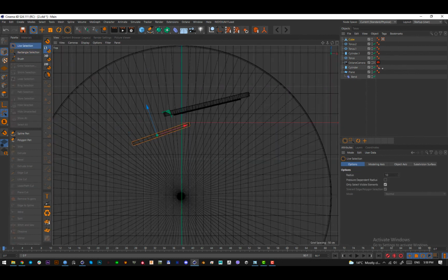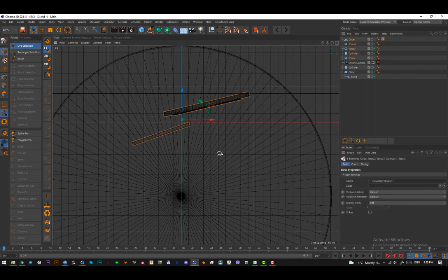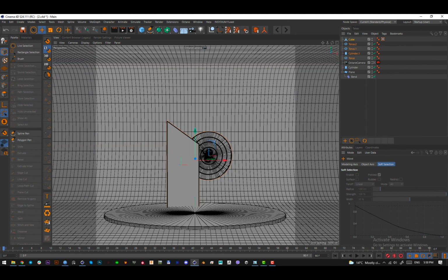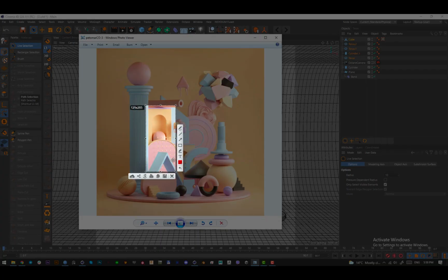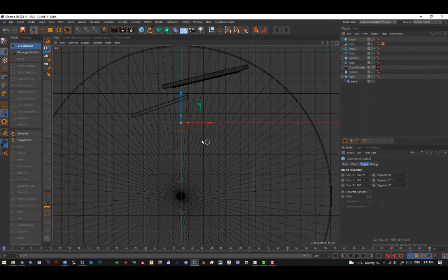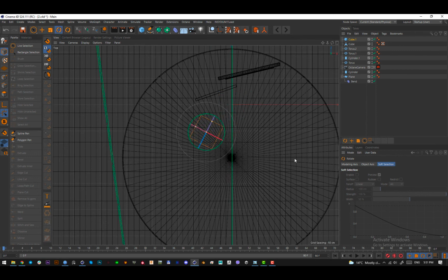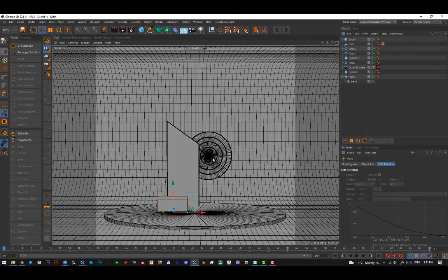Okay, let's now select everything that we have made here and just move it slightly to the back because we will need some space here. Okay, this is perfect. Let's now do this shape here. Actually, this shape is the only one that's visible, but let's begin. Okay, this is a cube. So I'll make another cube. Use T on your keyboard, press T, increase, put it somewhere here, and somewhere here. Increase its height, like this. Okay.